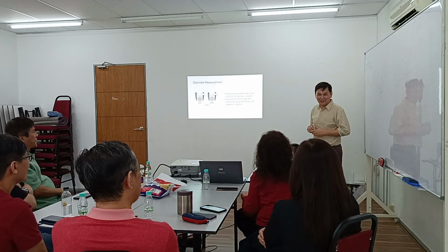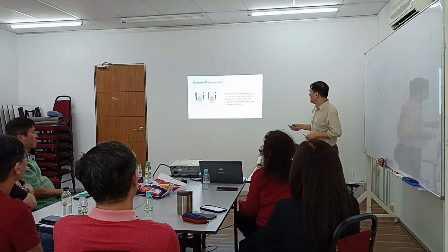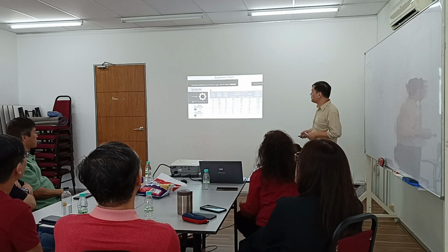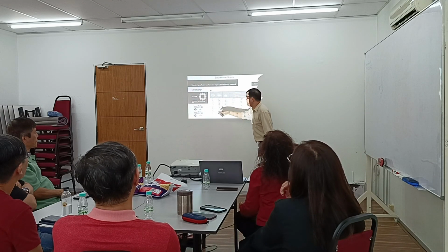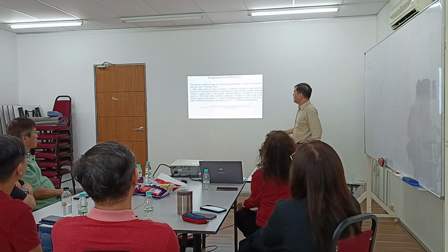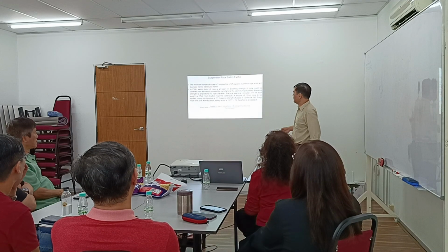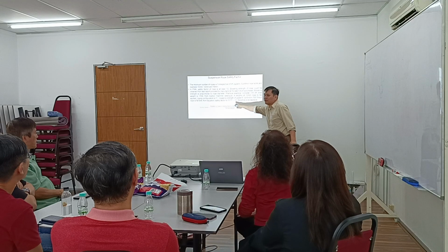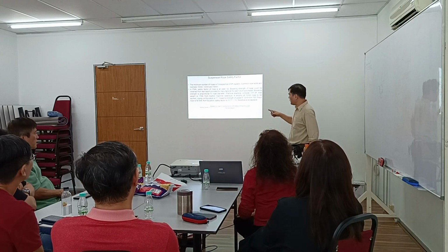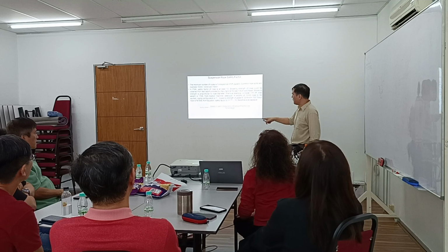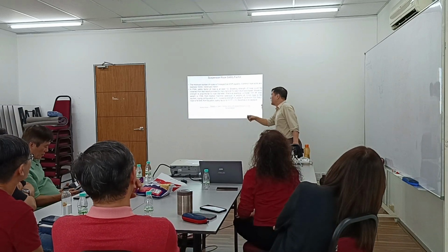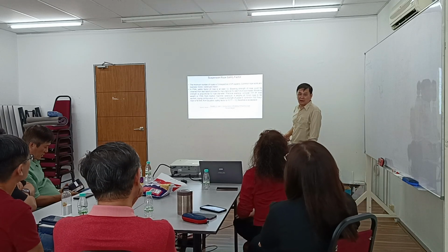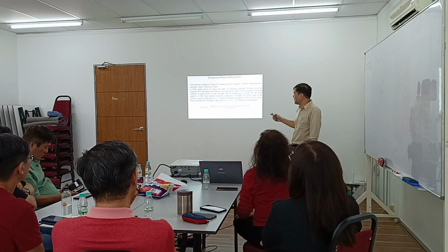So this is a suspension rope. Malaysia minimum 10 mm. The suspension rope safety factor is 12 times. How do we calculate? Very simple: number of ropes times roping factor times breaking strength of the rope, divided by full car weight. So this is the safety factor.